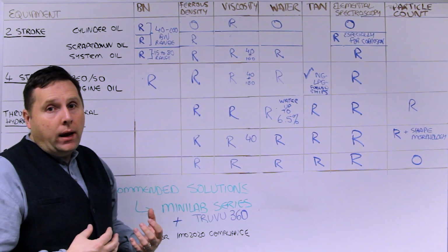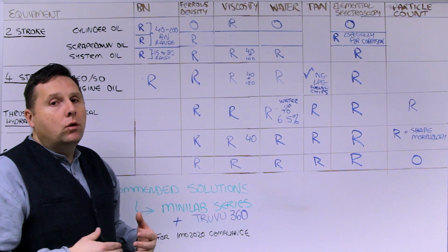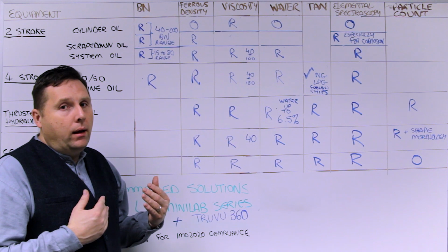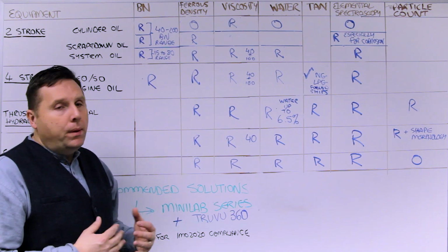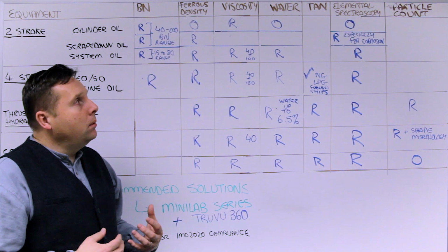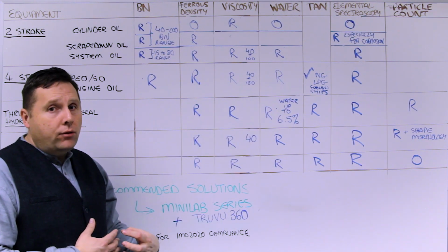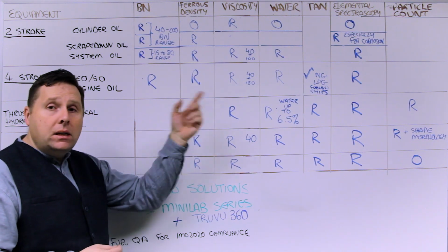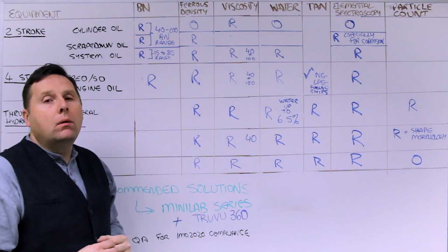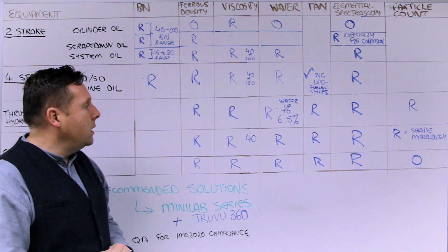With the sulfur cap that we mentioned earlier, you're going to see more and more engines that are powered by natural gas or LPG or propane-based ships. If you have those situations, you're going to probably see more of a requirement for total acid number, very similar to land-based natural gas compressors where TAN and TBN is required. Same thing would happen on the ships. So you'd look for the TAN result in those cases.